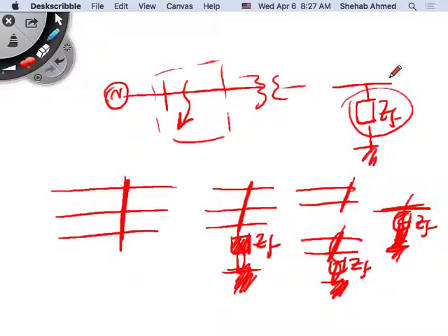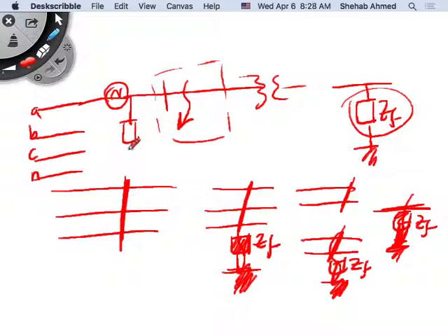And I took one phase to this room, one phase to the next room, one phase to the next room. So I have a three-phase system. This is my transformer. These are my transformer terminals, three terminals and my neutral. This is A, B, C, and neutral. I connected this to one room. Remember, everything we have here is between live and neutral, right? Live and neutral, and of course I have a ground connection.